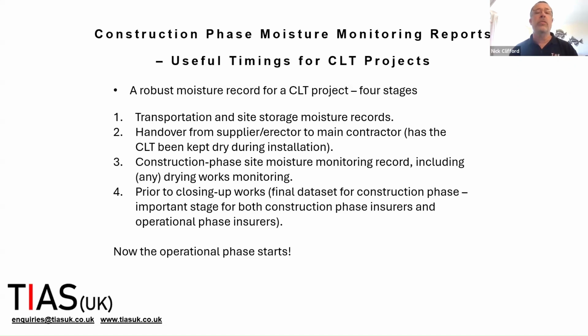Then we want some construction phase moisture monitoring for our moisture management plan and recording throughout the construction phase. So you need to make sure that you've got the right team involved. You can't just give one person responsibility for it, particularly on a big site. You need a team of people keeping their eye on moisture, regularly going around doing checks and recording the data throughout any drying works, if any are required. Hopefully not.